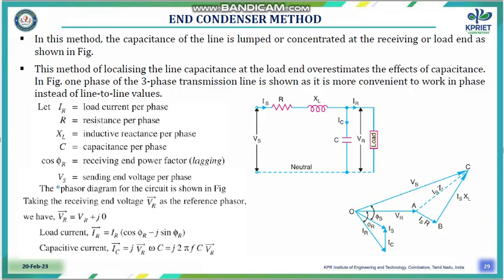And the resistance and inductive reactance are in the lines. This phasor diagram is similar to the short transmission line. The reference voltage has been taken as the receiving end voltage, and from that the receiving end current has been drawn.